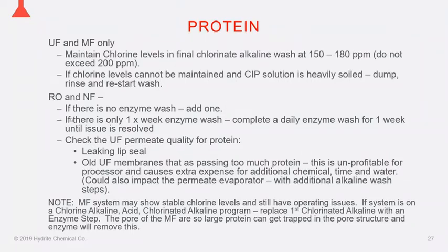And just remember, the real advantage behind enzymes is we aren't going to be putting any additional chemical stress on these membranes. The enzyme is going to only specifically target proteins and use all of its force against them. So the oxidizers that can be used on MFs and UFs, it might be cheap chemistry, but it's sort of a shotgun blast, see what it hits type of chemistry, whereas the enzyme for both of them is going to be a very targeted approach.